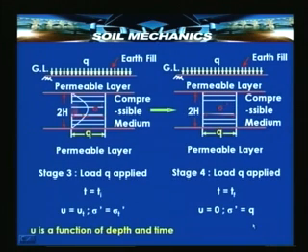Now, if we proceed further, we gradually reach the very last stage, where at t equal to t final, the entire excess hydrostatic pressure is totally dissipated, and the effective stress is equal to the applied load Q. That means the solids have now taken over the complete load from the surface. Now, let us go back a little bit. Have a look at the pressure distribution diagrams as well.